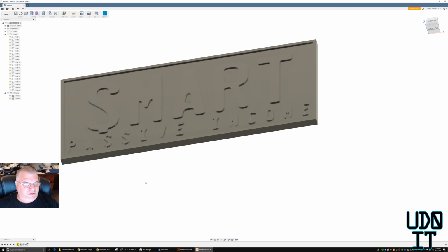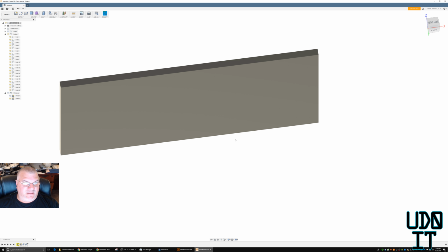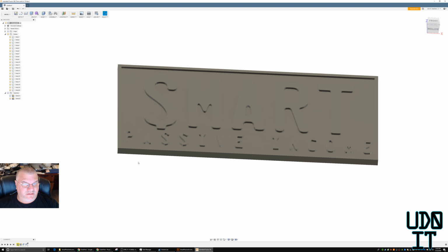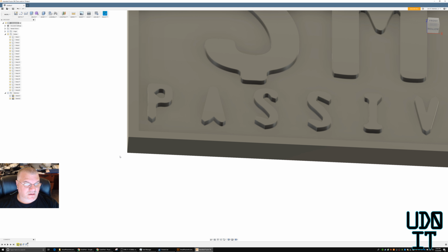So when I first extruded all these letters, I extruded them up vertically 1mm. But then I selected the rectangles, the border rectangle and the inner rectangle. I selected the area within that, and I extruded downward, -3. And so what that did was that allowed me to create this surface. Now there's a couple things that I want to do to this, and it's to create fillets on the inside and the outside of this.